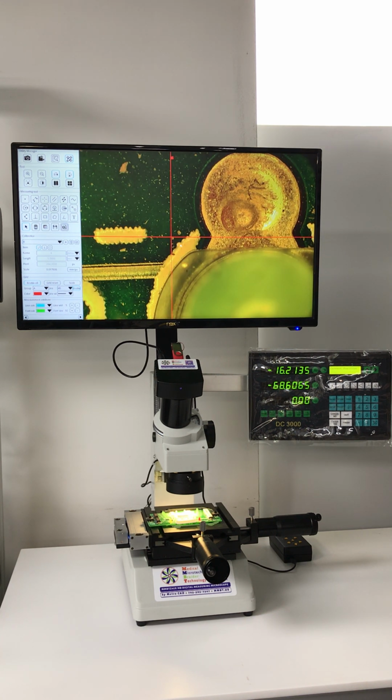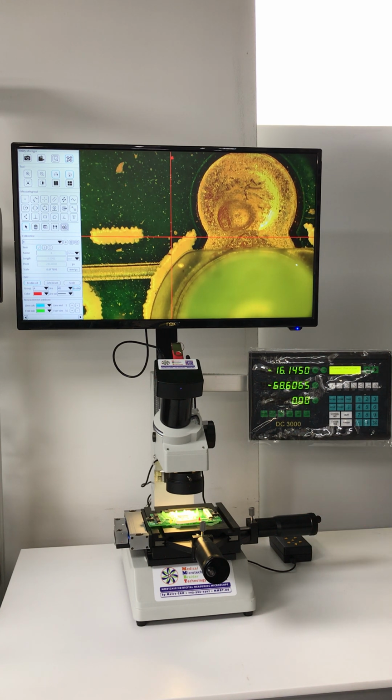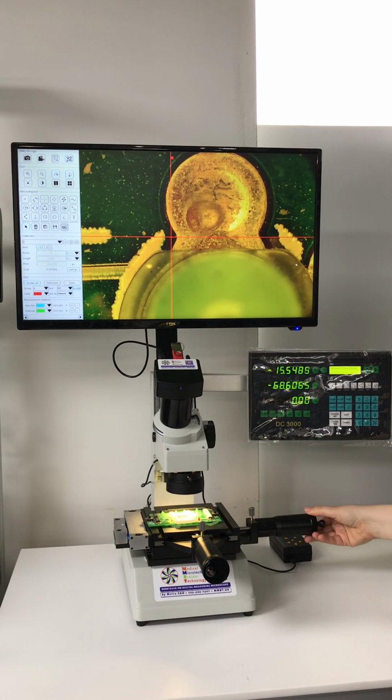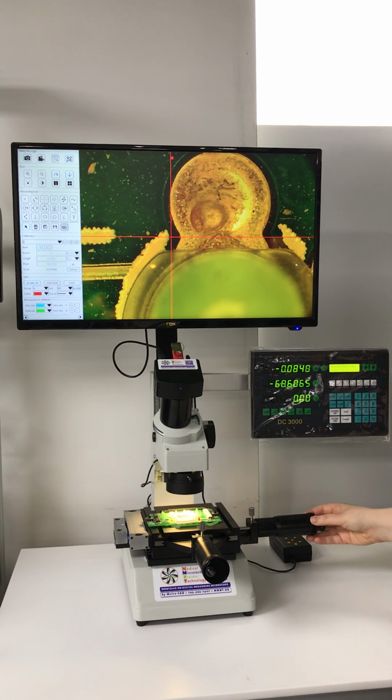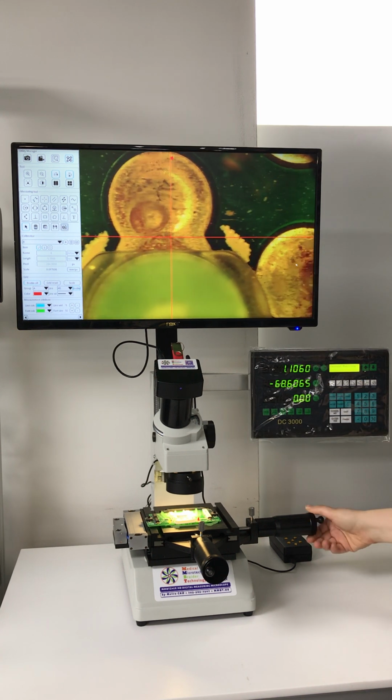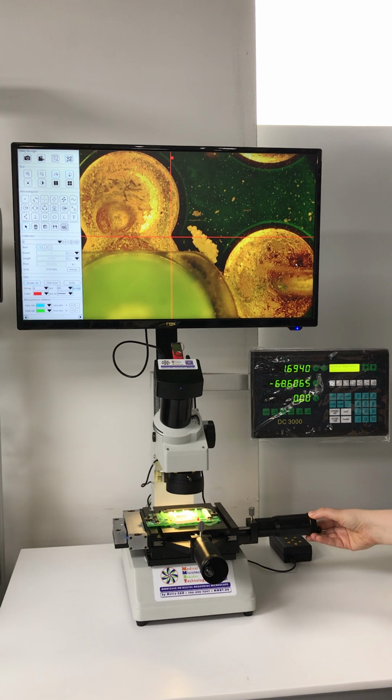Now we will focus on measurement. Again, this is an XY, so this one does not have Z. If you ever want to do a quick measurement, you can zero out your axis. So if I want to measure the length here, I will start at my one point, zero it out, move over to the other part, and I will get my X.